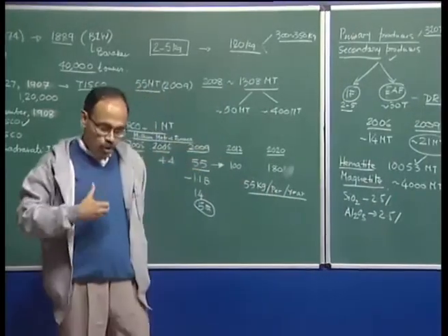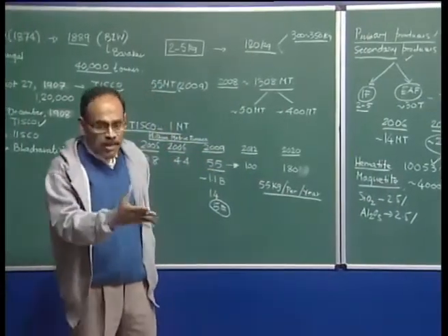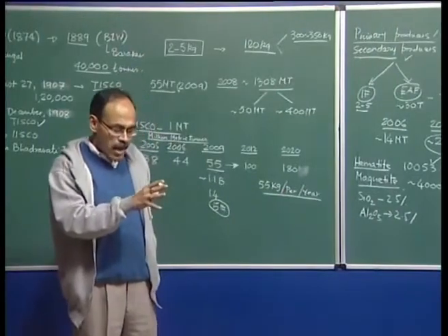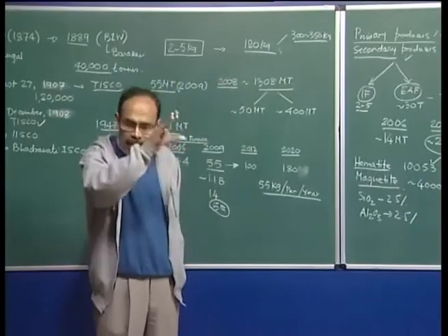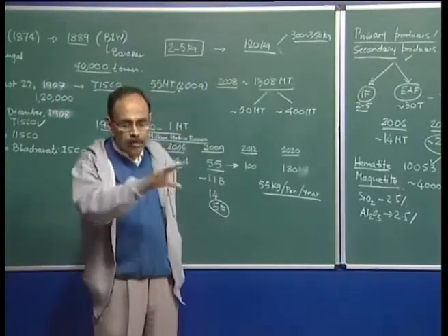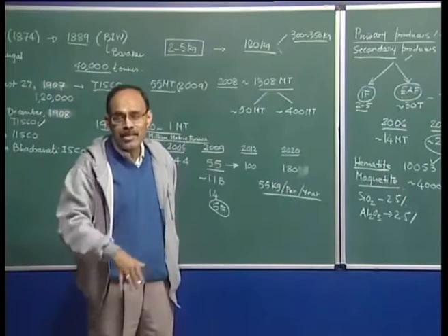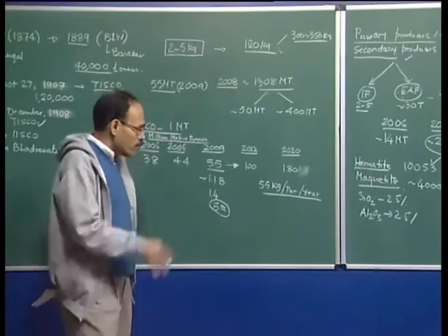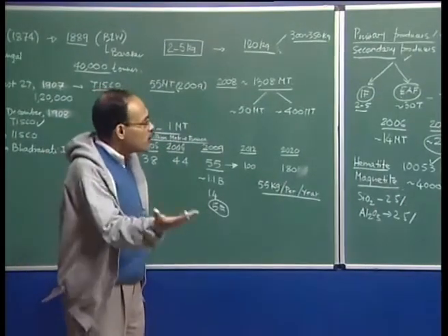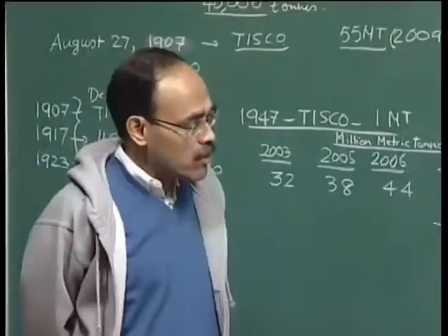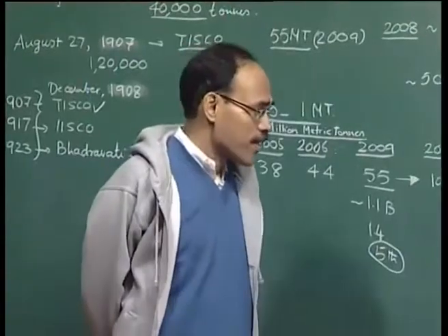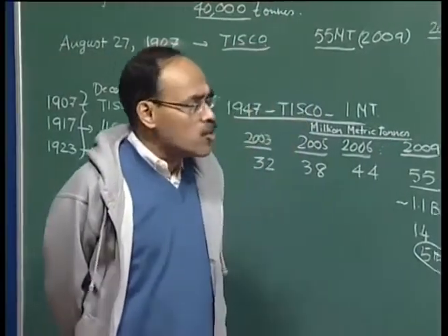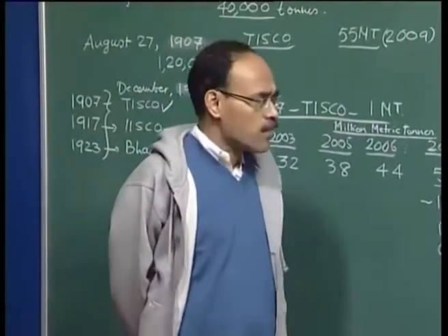So we have our coke, which is otherwise fine but contains a lot of ash, and this coke is mixed with the imported coke, which has a relatively lower amount of ash, and when you blend the two cokes, you get a resultant mixture which has intermediate ash, and which you charge into the blast furnace in order to have good production rate and coke consumption rate in the blast furnace itself. So there is no dearth of material as far as this is concerned.